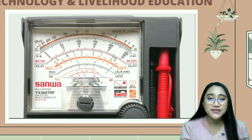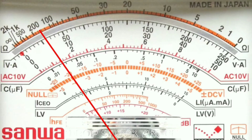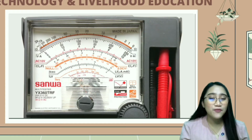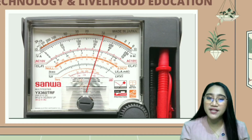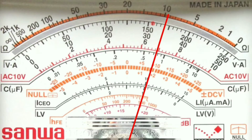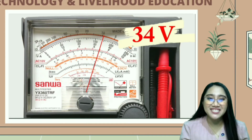Now let's try to read this. 0, 1, 2, 3, 4, 5, 6, meaning there is 6 volts in our reading. Did you get it? Let's try another example. What is the reading if our needle points here? Let's start at 30 because it is the nearest to the needle. So 30, 31, 32, 33, 34 volts.